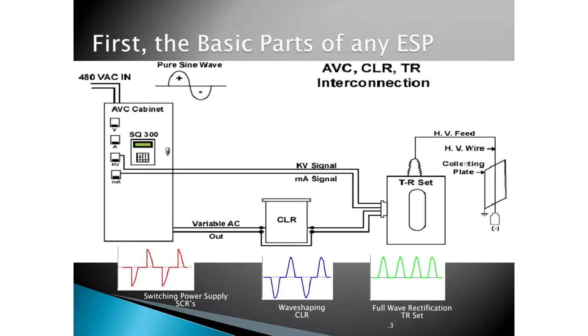Precipitators are really rather simple. They consist of four parts: the precipitator itself, the transformer rectifier set, the automatic voltage controls, and current limiting reactors. A precipitator is a dust collector. Inside that dust collector, there are rows of parallel plates, grounded collecting plates. Those parallel plates form gas passages, so there's multiple gas passages across a precipitator. Centered in that gas passage are high voltage electrodes.